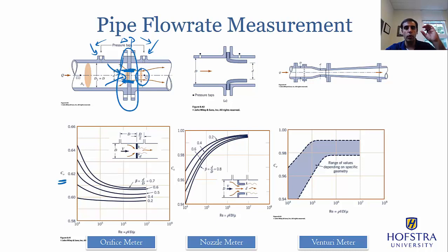So as the flow goes through that small orifice hole, it actually necks down a little bit more, meaning we'd get functionally higher velocities, right? And that's the vena contracta. In addition, we have some energy loss due to the flow separating here and swirling backwards. So those losses are the reason for a discharge coefficient in our formula.